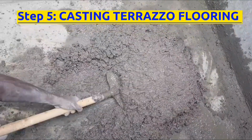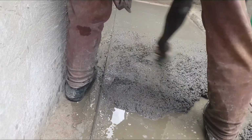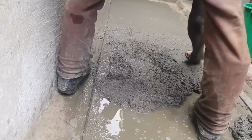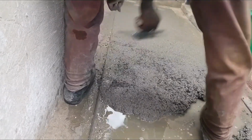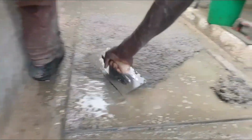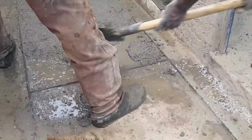The fifth step is casting terrazzo. Pour water first on the floor, then pour this mixture on the well-prepared surface. When casting terrazzo on walls or skirtings, water has to be minimal, whereas when casting on floors, water has to be more, so that cement in the mix amalgamates the upper part with the existing lower part.